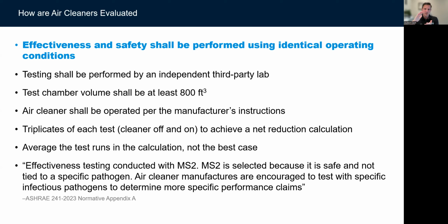Then you look at actual reduction, the sum of the device on and how effective it is at removing the particles or the pathogens. The average of the runs is taken, not the best case. And then the effectiveness testing should be done with something called MS2.